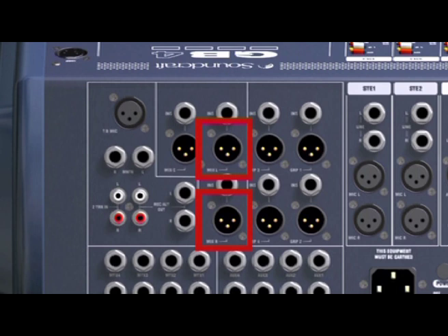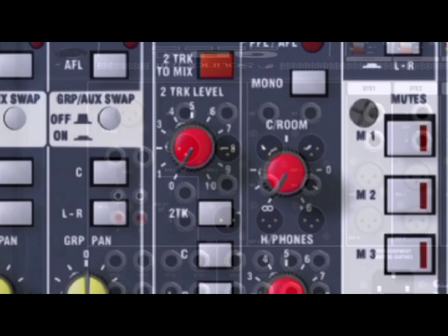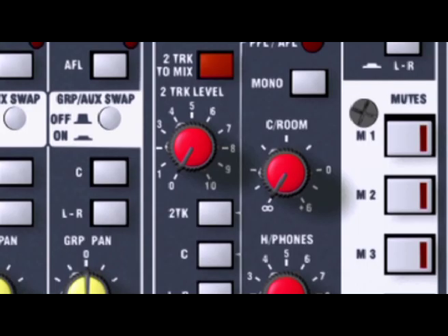You may find your mixer has mix insert points, which would be useful if you needed to connect signal processors across the whole mix. The control room or engineer's outputs are not sent to the auditorium but are normally used for an engineer's headphone feed or loudspeakers in a control room. You can monitor the whole mix from here, or any solo, submix from a group or 2-track tape return.